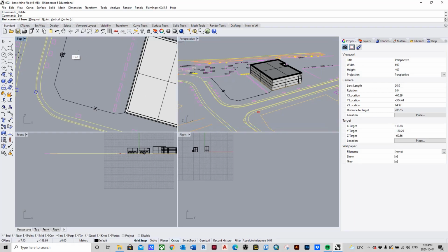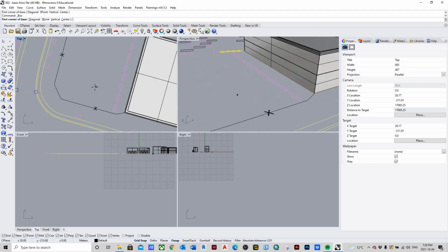Let's move over to our top plane right here, and we're going to move over to the box tool because we want those windows to be box-like. Now let's begin drawing our 2 by 2 chisel that we're going to use to Boolean difference away a hole for the window.